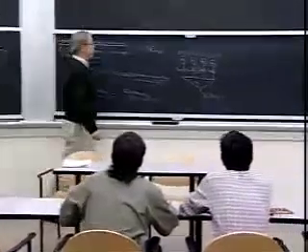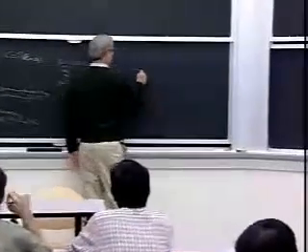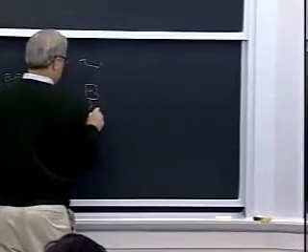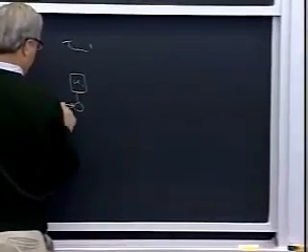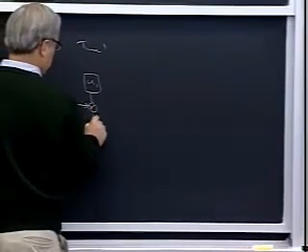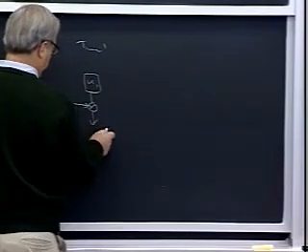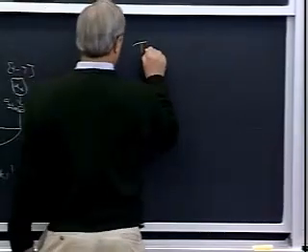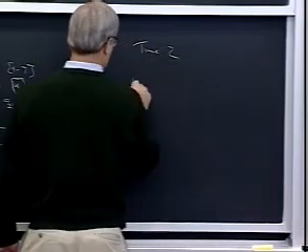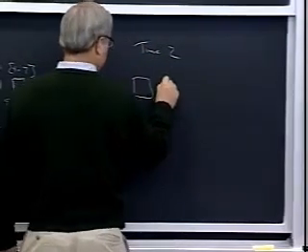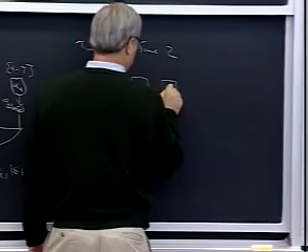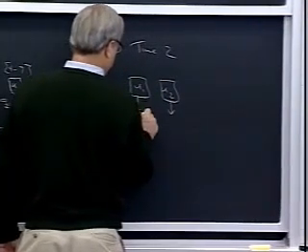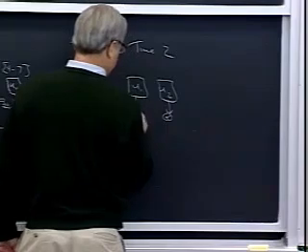All right. At time 1, it looks like this. Time 1, it just has U1, and we multiply it by G11, which is 1, and that gives me the output at time 1. There's nothing else that contributes. All right. At time 2, we've got now another input, U1 and U2, and we've got to sum the contributions from both of those times their respective coefficients.